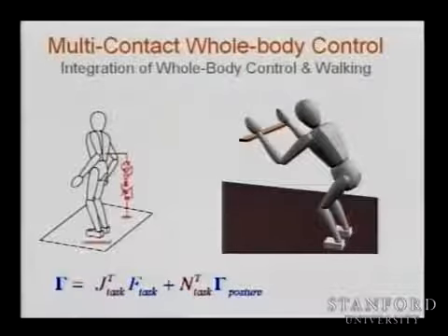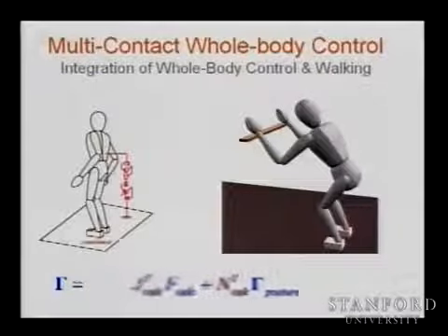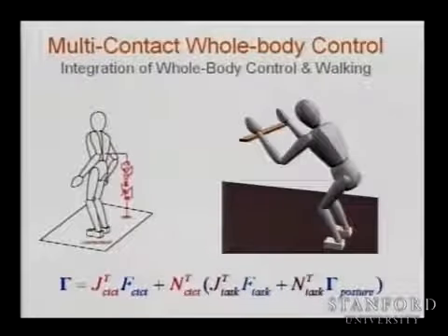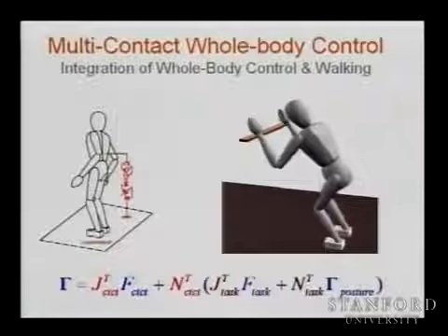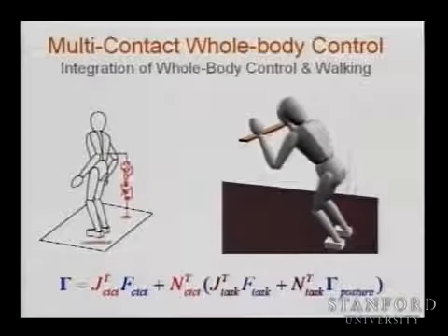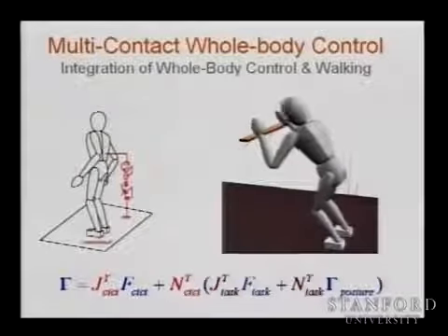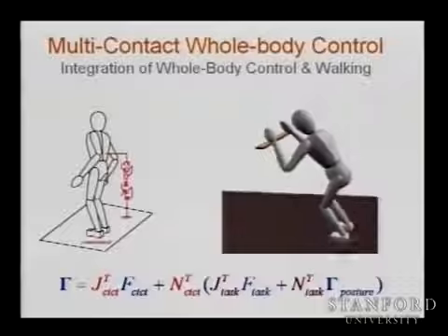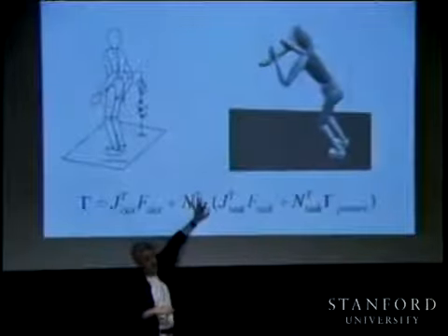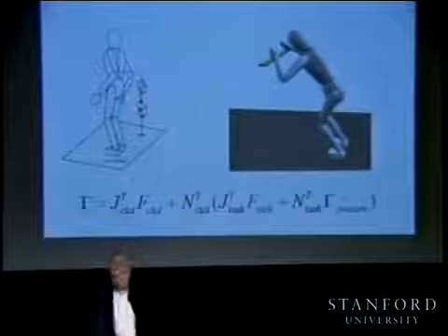Well, just say it. Say, I need to treat these as constraints. What are your constraints? These normals. Take the Jacobian, take the null space, and put it in. Now you know how to do it, right? Put it in the contact space. And then you are able to bring the two together. And now this motion will be consistent with the constraints, and you can control the forces at the constraints. If you remember in the beginning of the class, we talked about omega and omega bar. This will become your omega bar, and this is your omega in the multi-contact space.